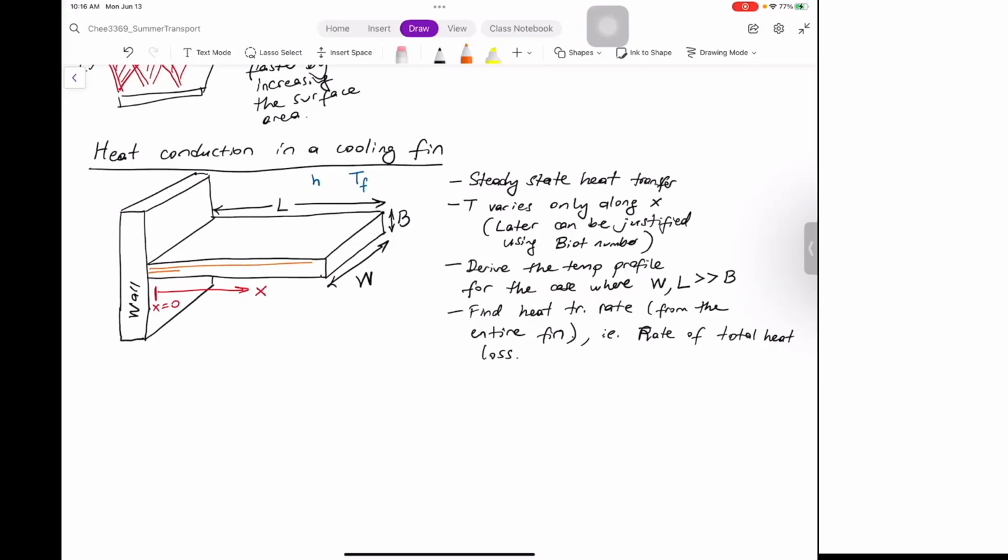If you take a shell like this, the temperature here is going to be different than the temperature here, so that's not a legitimate shell to take. You need to take it like this, because the temperature is varying mostly along the x direction. If you take a slice like this, you can assume that the temperature here is the same as the temperature here, and so on. So you can assume uniform temperature along your slice. That's my primary concern here.